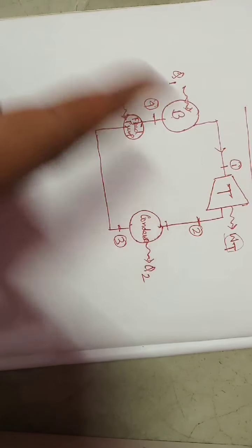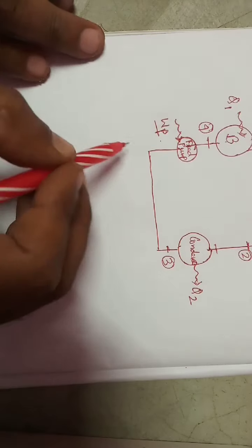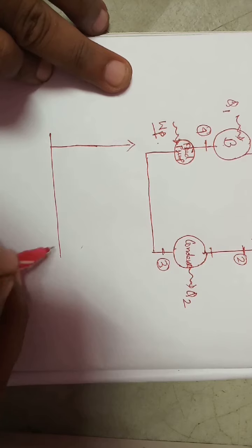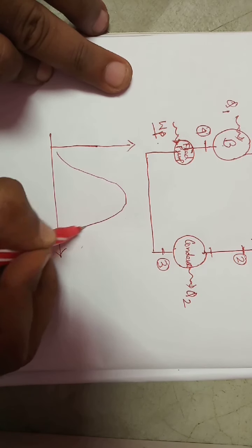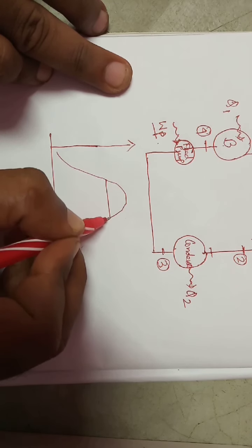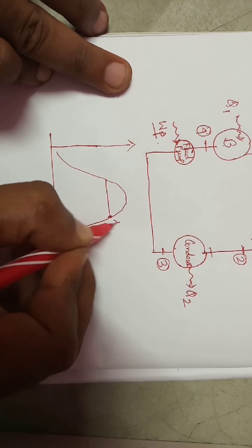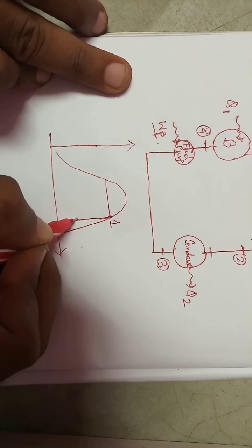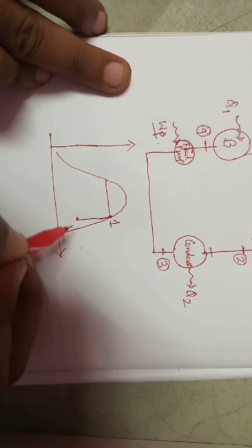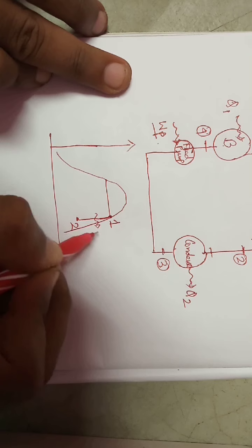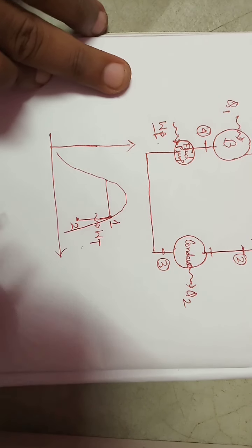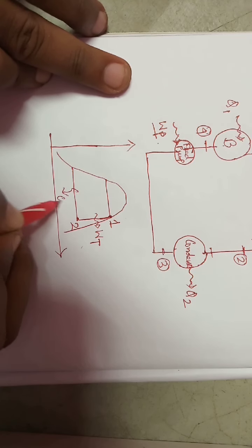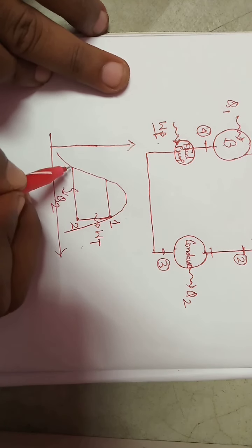And this typical diagram represents, as we have seen before, the TS diagram, where we can see this is the initial point 1. It's the turbine reversible adiabatic expansion process 1 to 2, which produces WT amount of work, and in the condenser it rejects Q2 amount of heat.